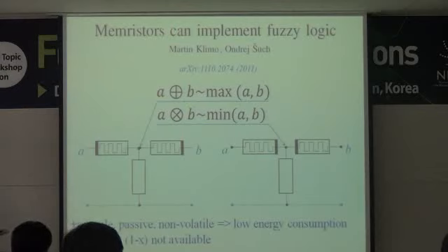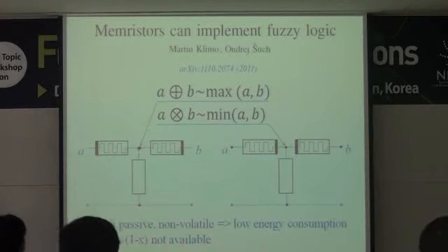Then these circuits can calculate the fuzzy logic function without any external power. The only power which is needed is power of inputs. Then this is the fully passive network, but of course it is impossible make the strong negation with passive network,